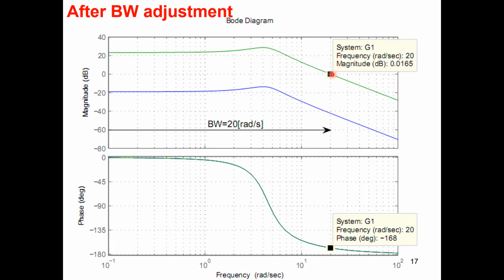So for that, you come down to this one and see your phase is 168. It's not 160 or 180. So therefore, you can be happy about it. The gain is 1. So one condition for the disaster is already satisfied.